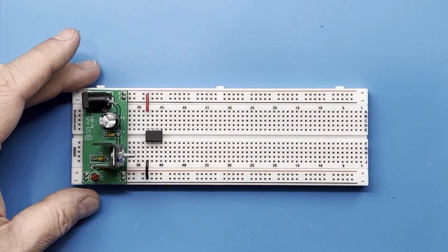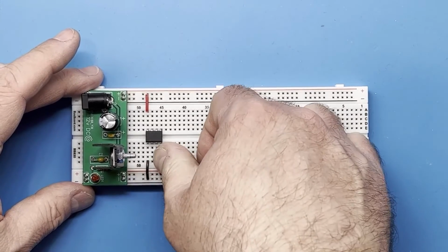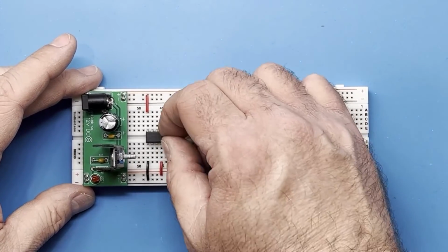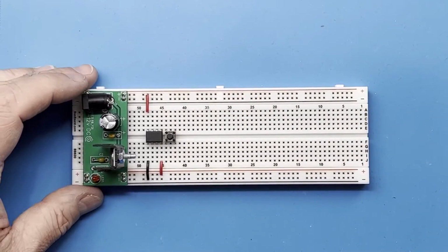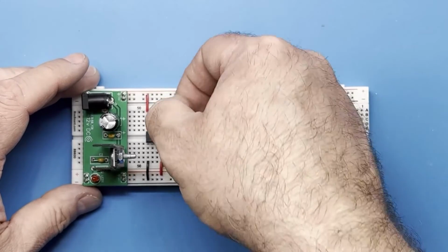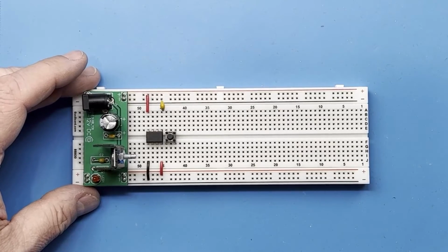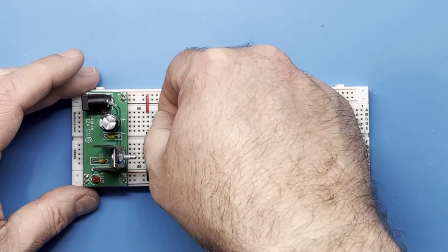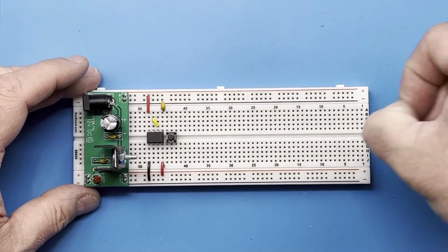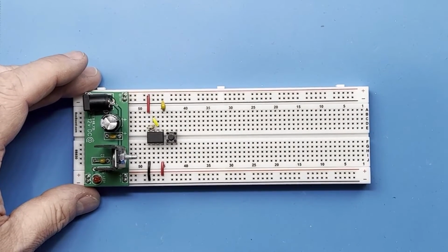And pin 4 is a reset, which is active when low, so I'll tie that to 5 volts so it doesn't reset. And then I'll add my push button over here. Now pin 5 is a control pin, but we're not going to use it, so it's advised that we decouple it to ground through a small capacitor. So that's what I'm doing there. And then I'll connect pins 6 and 7. Add a resistor between pins 7 and 8, which is providing power to pin 7, and a capacitor to pin 6 and ground.